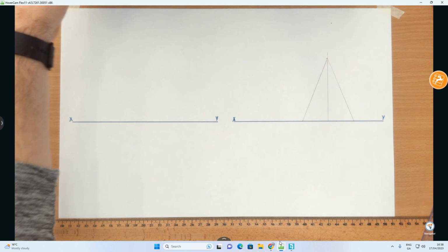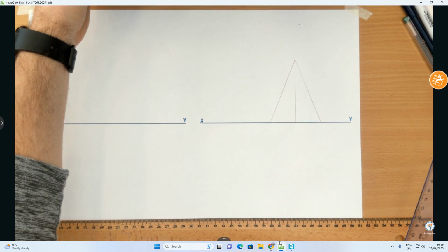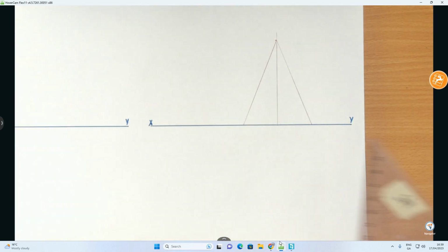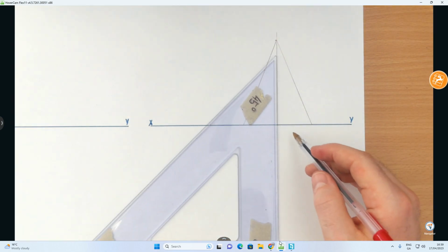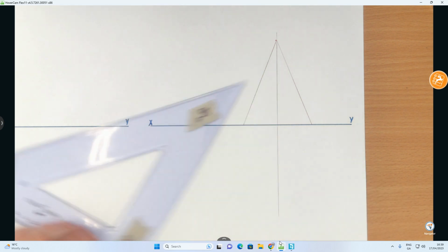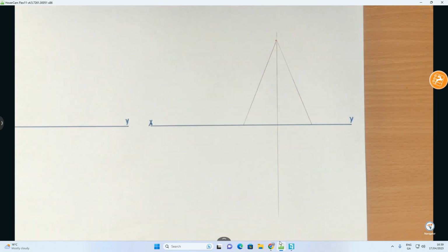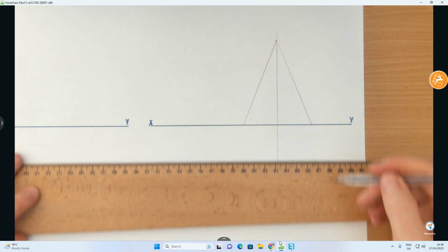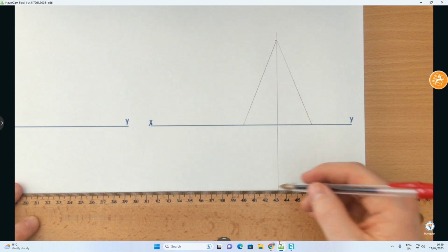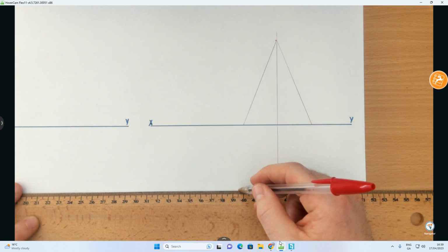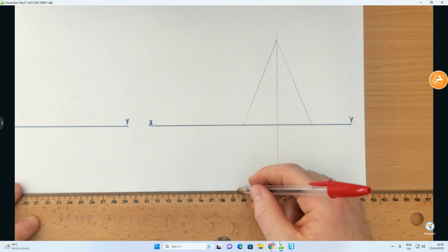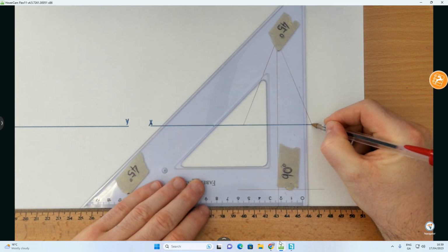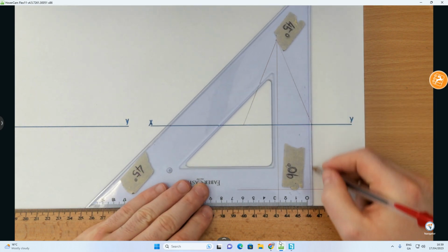In the elevation view, I'm going to zoom in on that one. Let's move this ever so slightly so we can see it in a little more detail. The center point of the cone, which we'll see in the plan, will be directly below the apex. It does not matter where I set up my axis line running across. Just don't set it up too close, because we have to draw in a circle with a diameter of 64, a radius of 32. So we'll do the line about there going across, and then to get the radius from here, draw a straight line down.